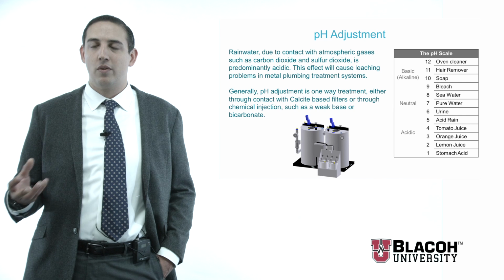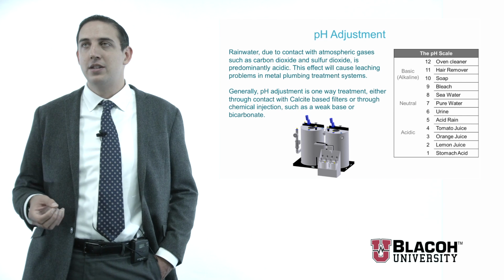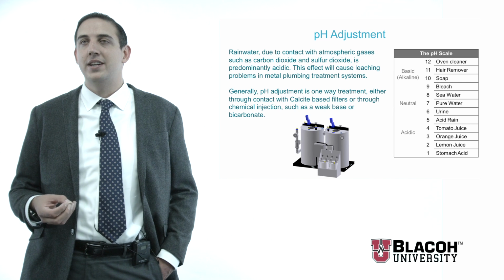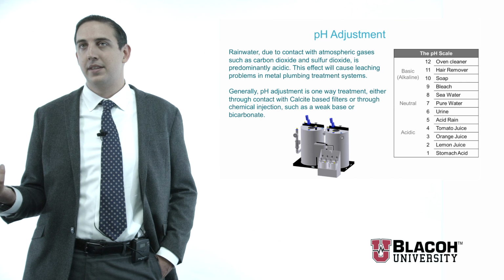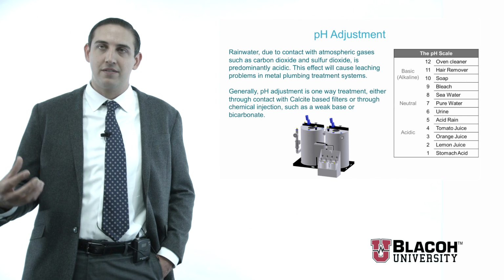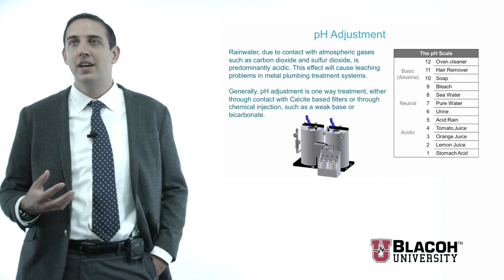You really want your rainwater ideally to be neutral in pH. This will prevent metal contamination from your roof from getting in, and also prevent damage to a lot of your downstream piping in the system. If you have any metal, or if you're using it for flushing fixtures, any kind of copper or brass you use in your actual flushing fixture header.